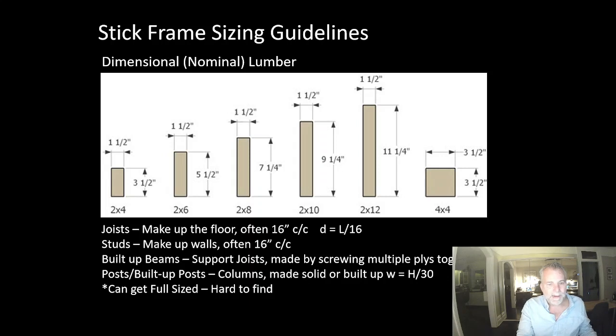Some sizing guidelines. So these are the standard sizes that are available. I talk about 2x. So you can see the first one, 2x4, is nominally 2 inches wide, which is 1.5 or 38, by nominally 4 inches deep, which is 3.5 inches or 89 millimeters.